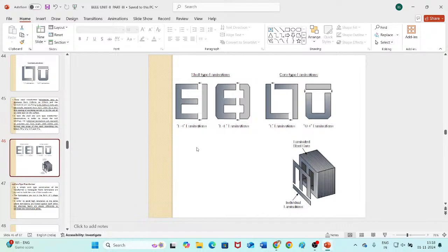These thin sheets, their thickness will usually be around 0.25 mm to 0.5 mm. These laminations are fixed together by studs, rivets or bolts. They are staggered one above another, fixed together by bolts, and provided with proper electrical insulation. So this is it, the construction and the